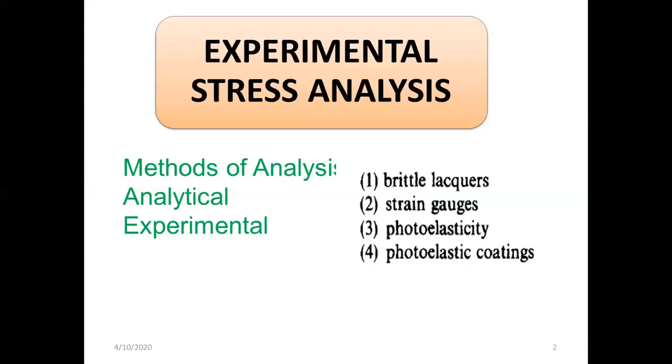For time history analysis, we need input data. What do we need as input data? We need the nonlinear property of that particular material. Suppose masonry, and the masonry properties vary from place to place. So we can't rely on the properties that are available in the system or in software like STAAD, SAP, Abaqus, etc. For that we need to calculate these properties, and these properties cannot be calculated until we perform the experimental stress analysis to obtain the stress strain curve of the particular material, masonry in our case.